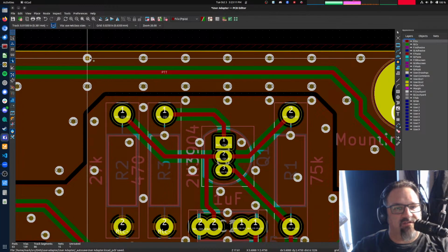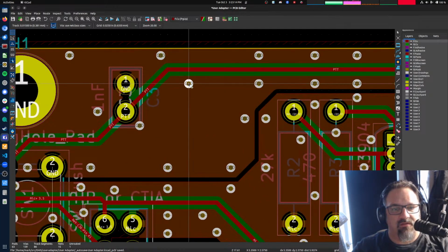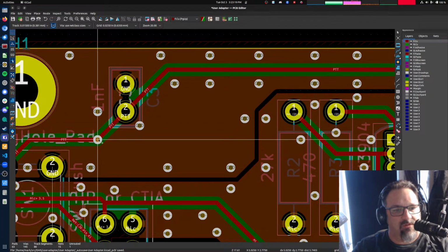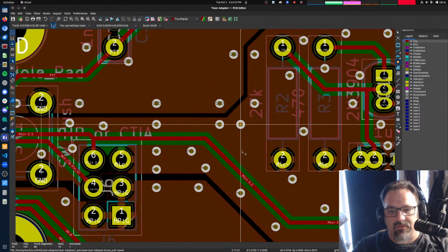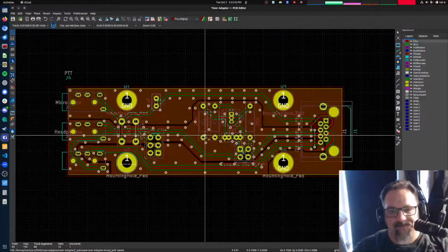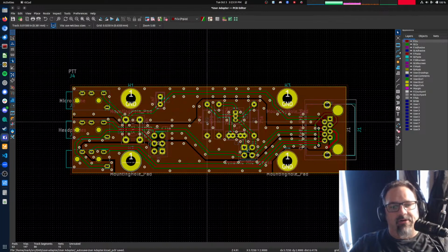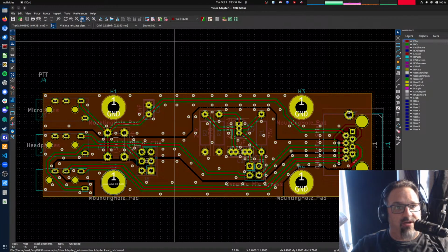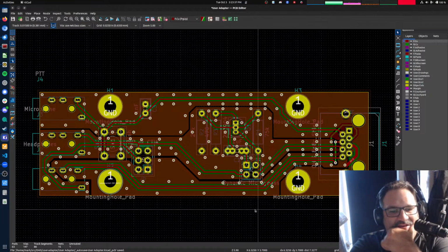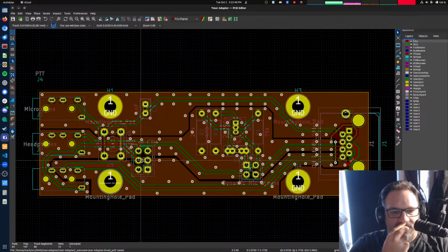We don't need that many vias. But, you know, they're cheap. Okay. So, let's look at this thing from on high. What do we see? I got a lot of silkscreen work that still needs to be done. I should probably move that jumper to the right some, space it out from the button.